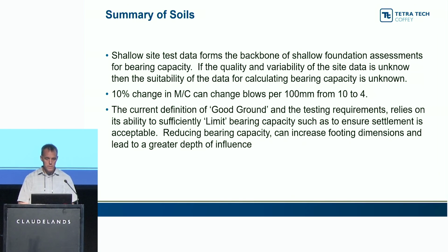I think one of the things I'd like to see is that the definition of good ground gets changed a little bit, so it's differentiated from the bearing capacity and the bearing capacity calculations. This is so that it's clear that when someone's providing you this good ground or this limiting bearing capacity, it's quite different from a traditional bearing capacity calculation, and not to be confused.